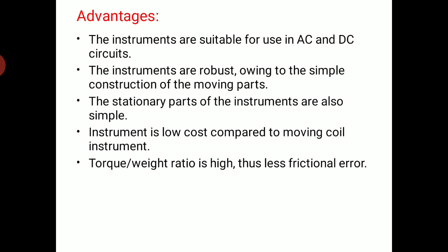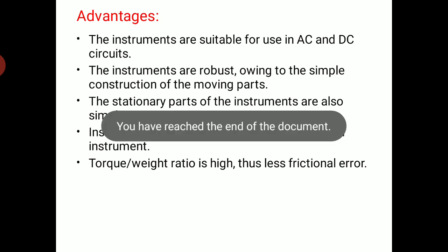So, advantages: it is used for both AC and DC. The instruments are robust owing to their simple construction. The stationary parts of the instruments are also simple. The instrument is low cost compared to moving coil instruments. The torque-to-weight ratio is high. It reduces frictional errors.